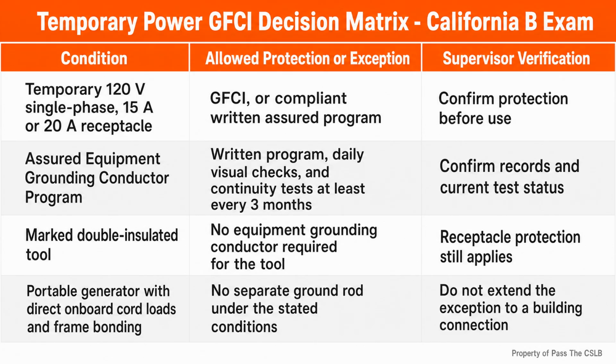If the pour proceeds, the electrode condition becomes concealed, and the intended connection may no longer be available for inspection or correction without rework. The better field decision is to stop the sequence, complete the electrical coordination, verify that the approved continuity connections are complete, and obtain the required inspection before placement.